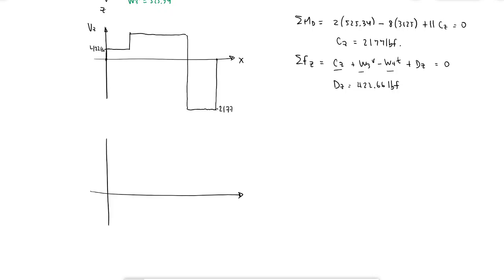So a slope of 422, a higher slope of something, 500 plus 400, and then going down to this point. This point where gear 4 is what I'm interested in. That would be equal to this distance 3 times this force. This value is just that area, which is 3 times 2,177, which is equal to 6531 pound inches.